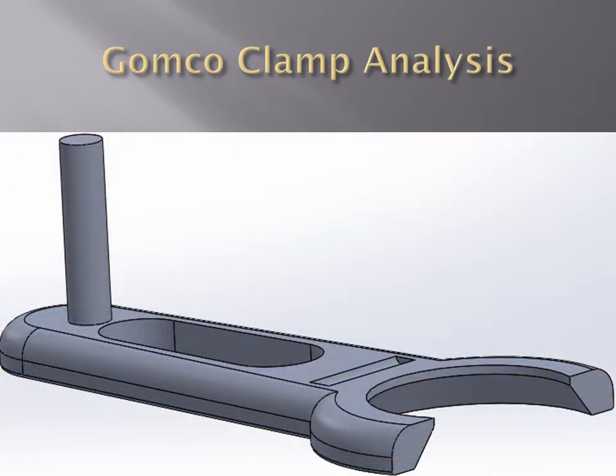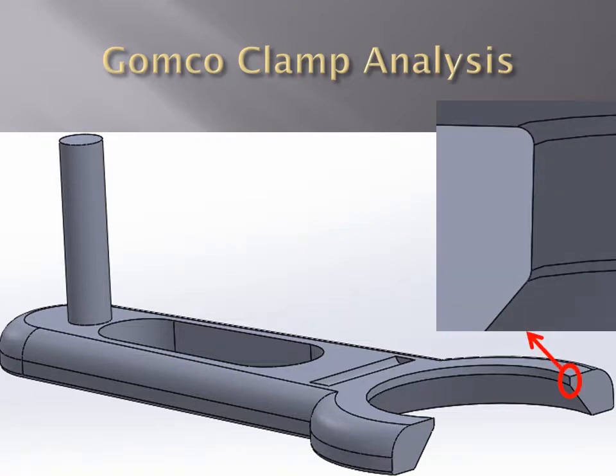If a section view is taken of the base plate, the anvil geometry is revealed. The anvil is a very small machined land which can be seen if the anvil is enlarged. However, because the anvil itself is a flat surface, the stress distribution will be constant across it.